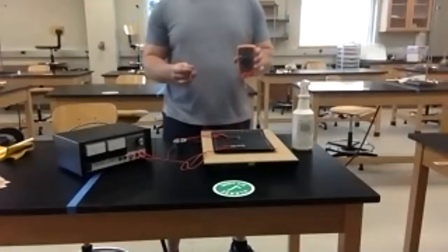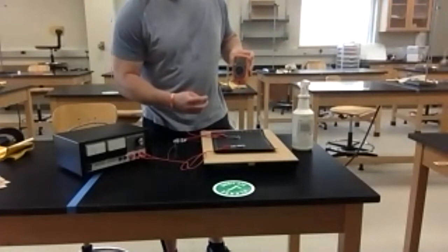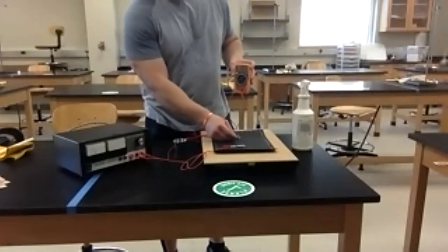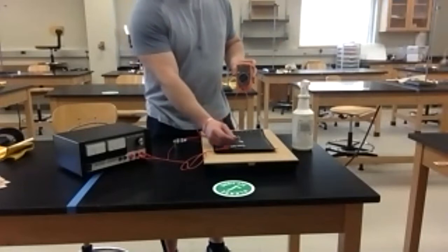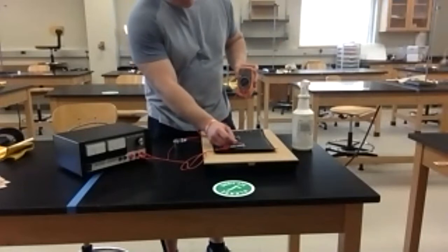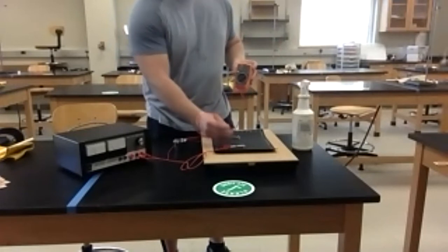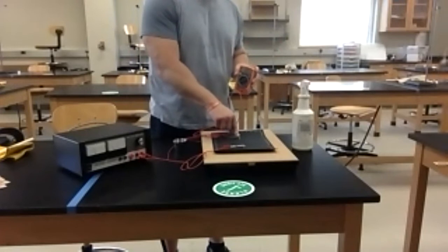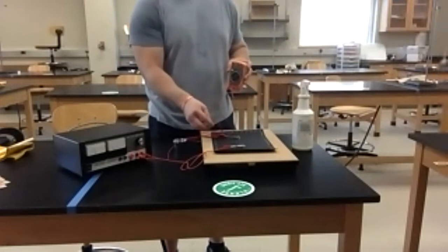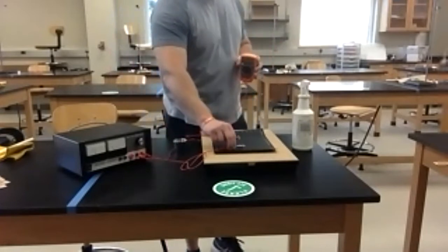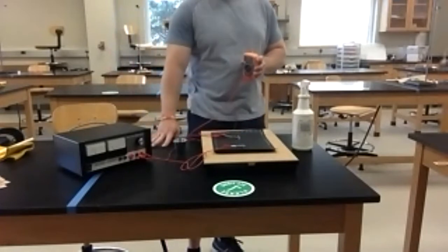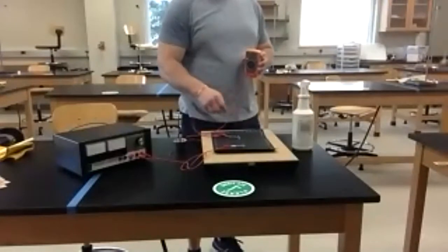And then what this is going to do is it's going to measure the potential difference between the two. So for example, if I touch the prong, which this is at, it should read 0 because I have 0 potential difference because I'm touching the same thing. But if I touch the other one, then I'm going to measure a 5.5-ish potential difference. So that means there's potential difference between here, which is the 0, and this one, which is at 5.5 volts. Now, all we're going to do in this lab then is you're going to have an extra piece of white paper, which has exactly the same grid on here.